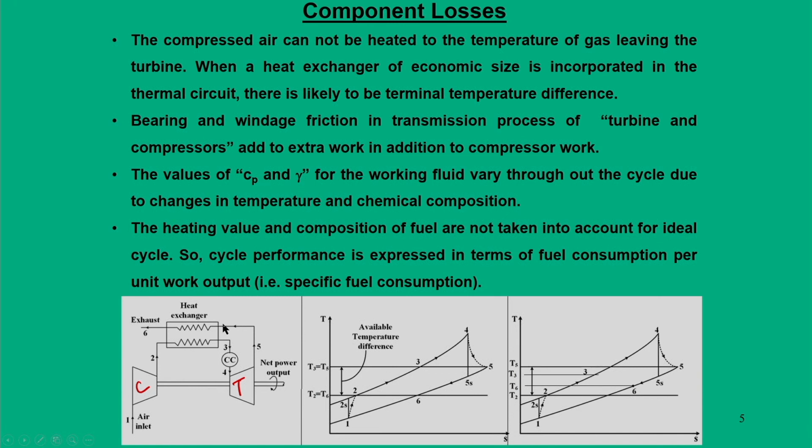In the last class also we mentioned that the Cp and gamma of the hot gases in the turbine have different values because they involve chemical compositions and high temperature changes. Because of this, we have to take the variation of Cp and gamma into account. Of course, Cp and gamma also vary with temperature, and in the entire gas turbine unit the temperature of the cycle routinely changes.